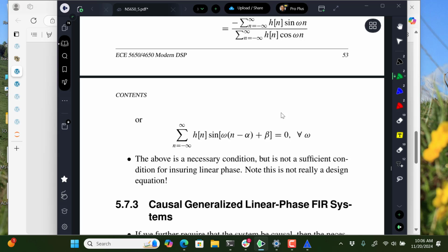You come down to a condition like this that says, if I want to build a filter based on a sinc function, but I want to have the condition that it's causal, I want to have the condition that it's linear phase, you end up with something that looks kind of impractical. It's not a design equation. How do you work with that? You think in your life so far you'd say brute force, I'm just going to try. But if you see something that looks kind of insurmountable, even if I put a computer to work on this, it seems like it could be a long time figuring out by trial and error what's going to work.